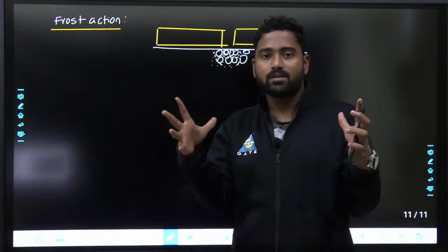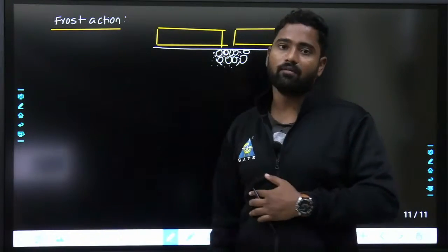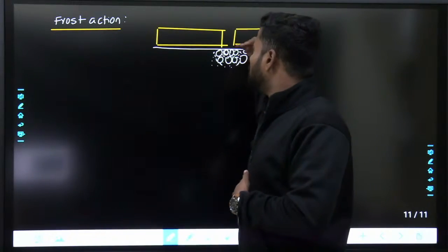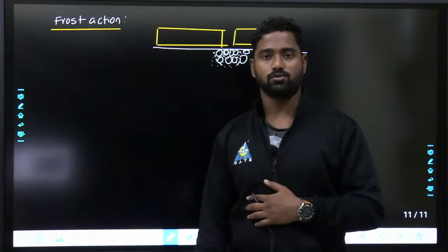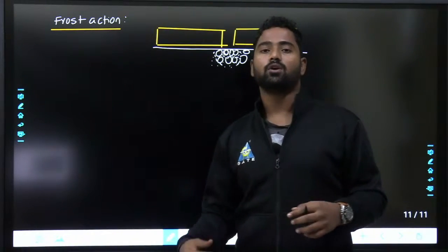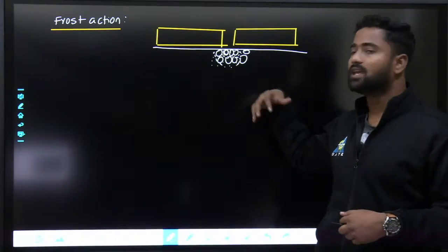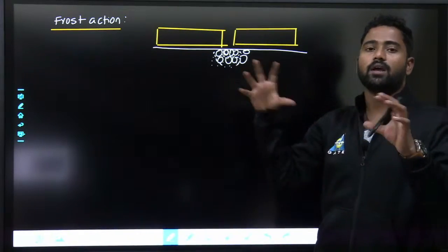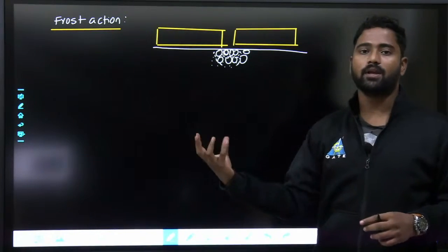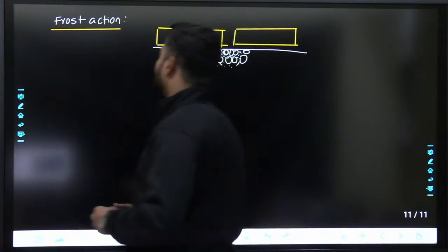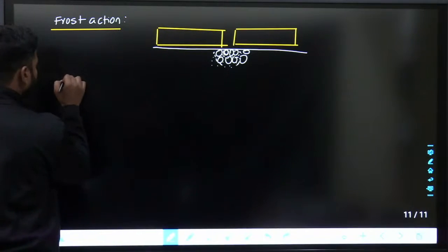Generally, not only in rigid pavements, you will see this in flexible pavements also. Fine, that is called frosting. Because of frosting, heaving action develops. Heaving means increase in the volume. Fine, and cracks will be developed. That is frosting and heaving action during winter seasons.